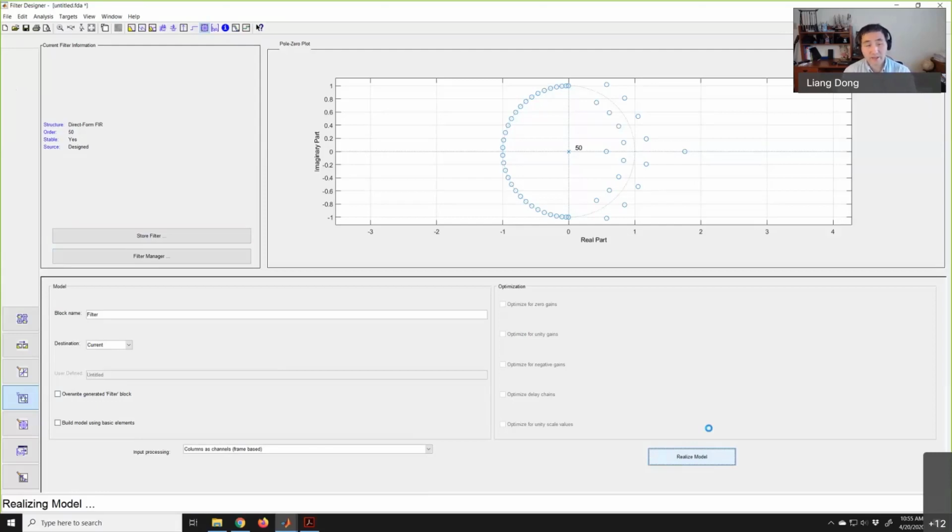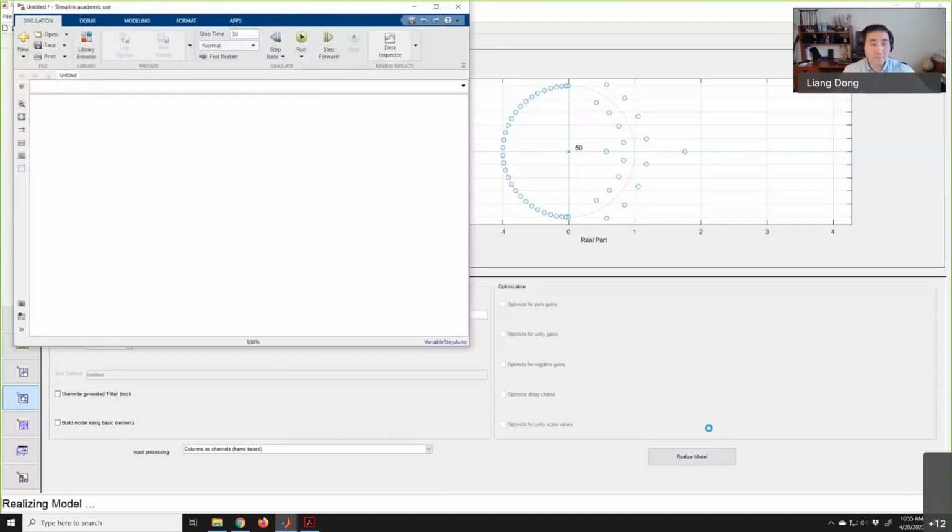We understand the specifications of the filter, how we design it starting from the ideal case, and then we define some non-ideal limits: the ripple, the band, the transition band. Using those to generate a filter that can work in Matlab. Okay, so now it comes out with the Simulink plot.